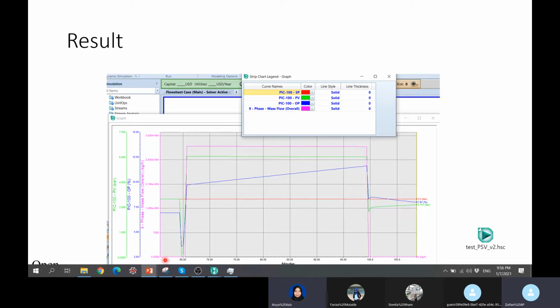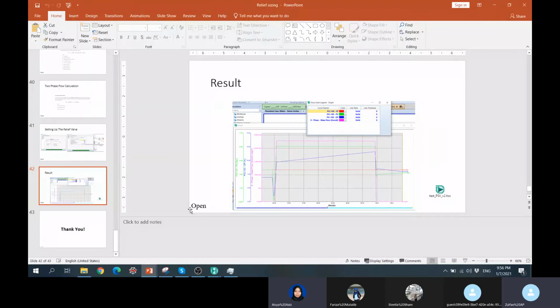Because this was zero, the flow rate through the PSV is from zero, and when the pressure is about 4.5, it goes up. So at this point we have to see where the pressure goes to 4.5, somewhere there, and then the PSV instantaneously goes up to release the pressure. So that's basically what happens, and then we can just rerun this and see.